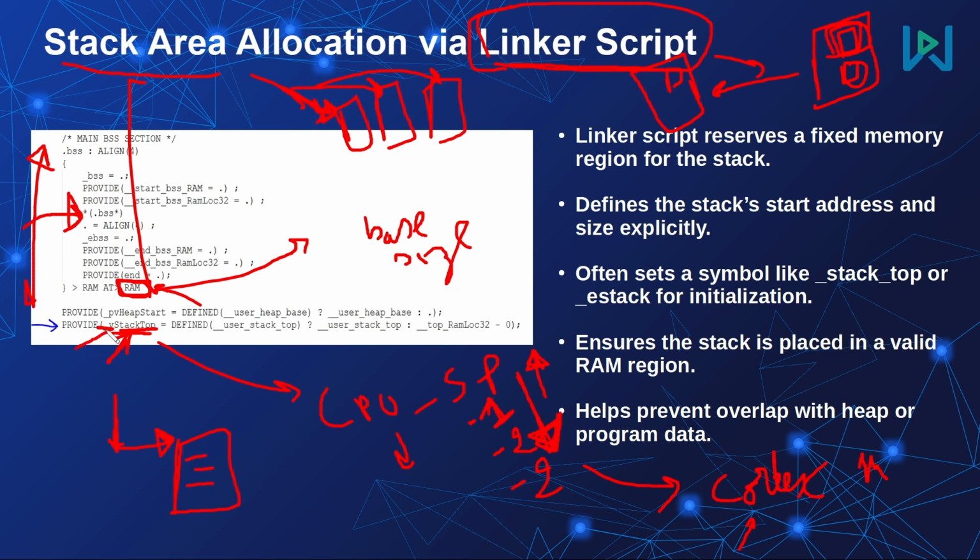Here, as you can see, we have initialized the symbol stack top with the top of the memory region that will be allocated to our stack area. So it can be this one or this one if the user provides this as input to our linking stage.